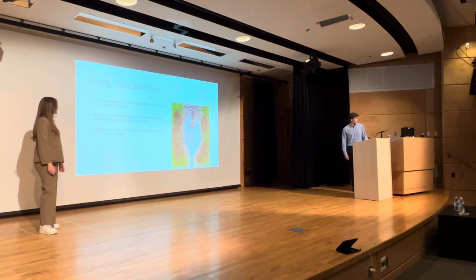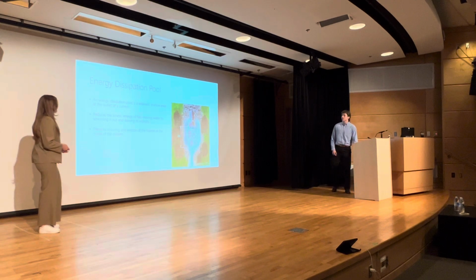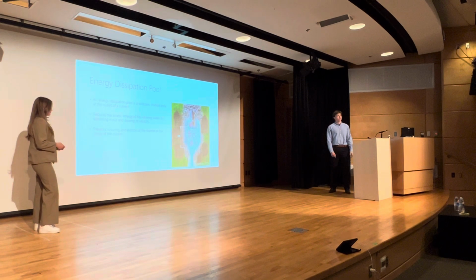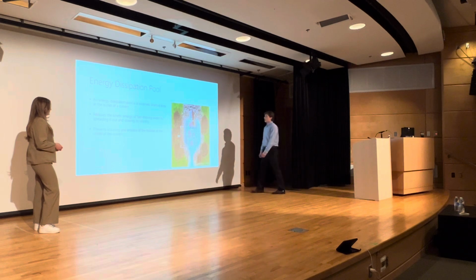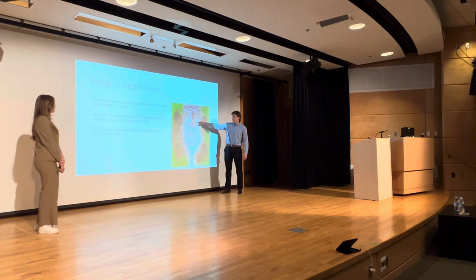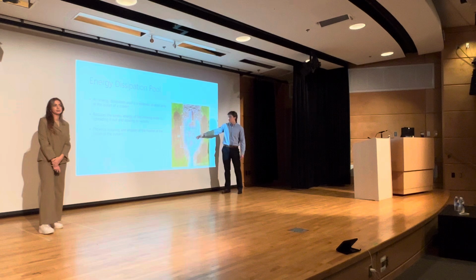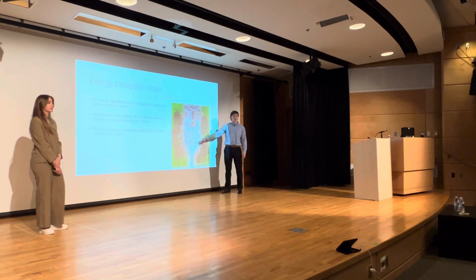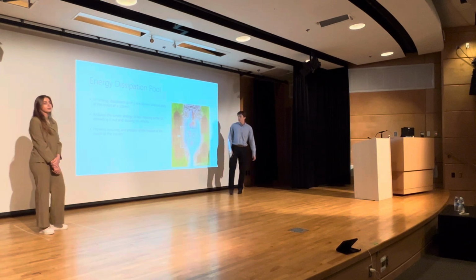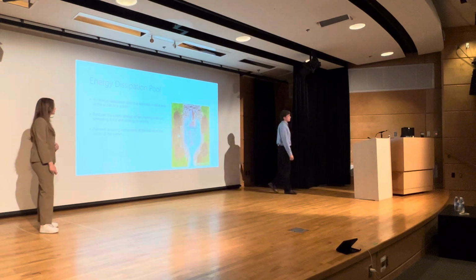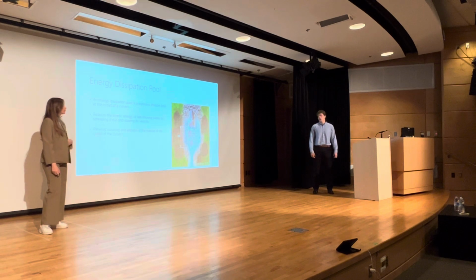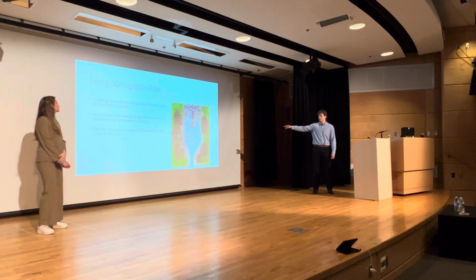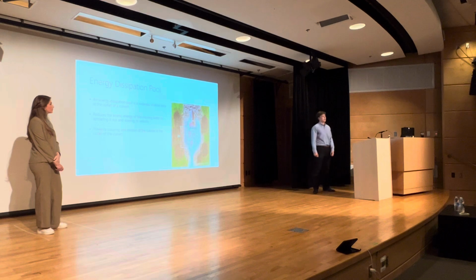And finally, energy dissipation pools. This is a widened shallow area at the outlet of a culvert. It's used to dissipate the outlet flow velocities to prevent erosion and scouring of the nearby habitat. The width of the dissipation pool would be 2 times the diameter of the culvert, and the length would be 3 times the diameter of the culvert. The dissipation pool is formed with riprap stone to further prevent erosion and degradation of the habitat. And there are 3 boulders placed in the center of the dissipation pool to also manage the velocities.